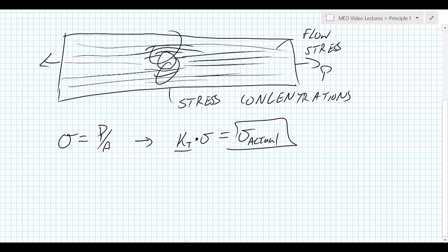In practice, what that looks like is we know the loading F equals 100 pounds, for example. The area equals, I don't know, how about 0.25 inches squared. Therefore, our normal stress from that would be force over area.